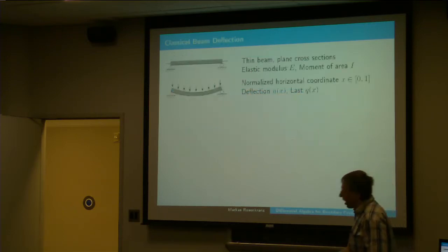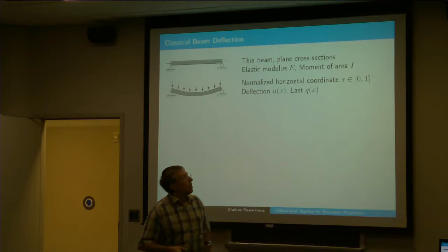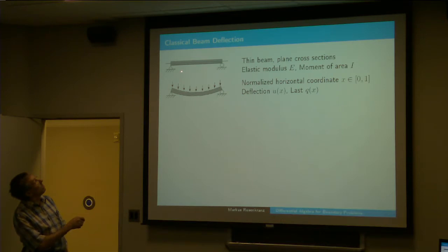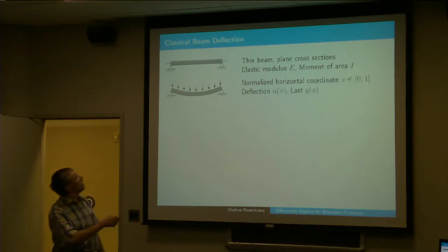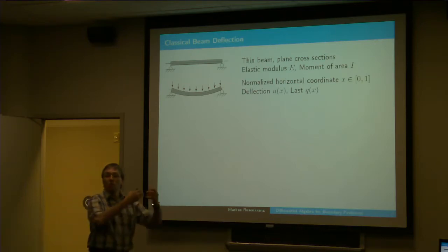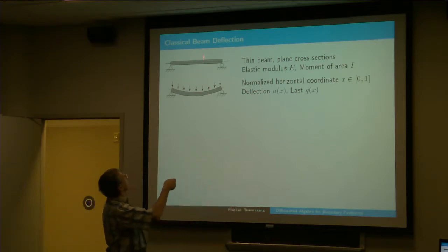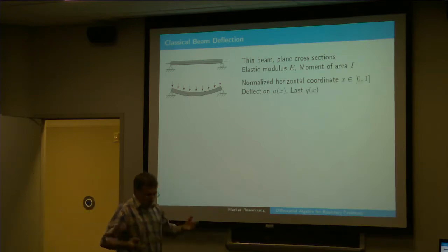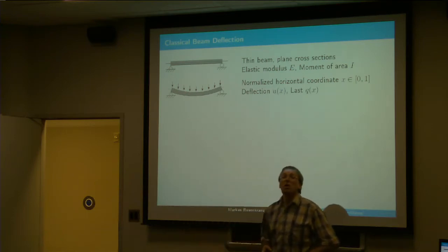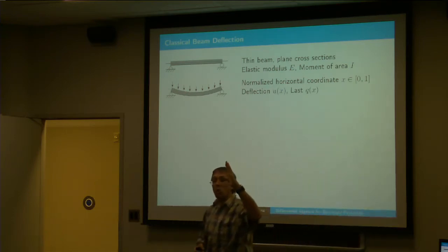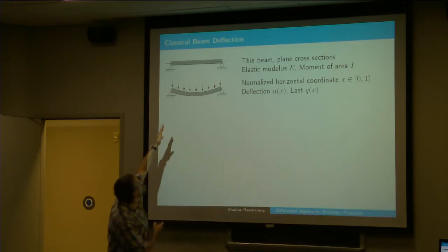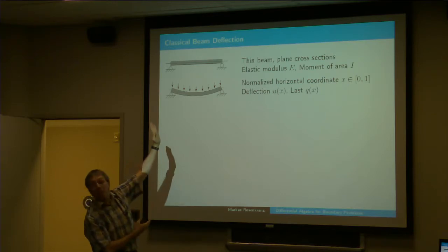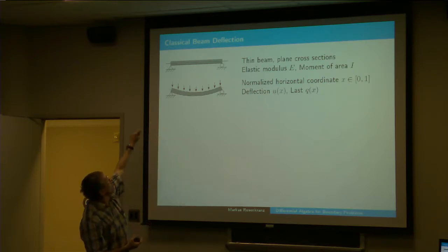Right, yeah. So let's just start with some classical example where all these terms like forcing function really have the natural meaning. If you look at the beam here, and we assume it's a thin beam in the sense that the longitudinal extension is very large compared to the lateral extension here. So essentially it's one-dimensional, mathematically speaking. And engineers, in the first approximation to describing this, like to assume that the cross-sections always remain plane. Yeah? So when this bends, obviously the cross-sections will also be bent, but the assumption is that it will still be orthogonal to the so-called neutral line.